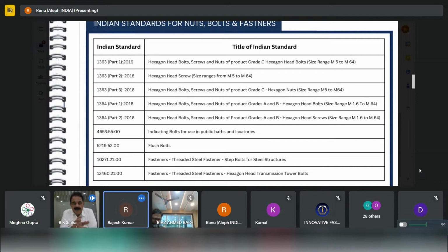First, you will have to see whether the standard permits anything other than the length which has been given in the standard. And if it permits, then what shall be the tolerance on these lengths? As you are saying, there will be a difference of 1 mm or 2 mm, something larger they're asking. In that case, what shall be the additional tolerance required for that customer requirement, provided the standard permits that?